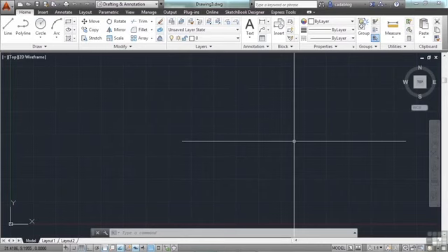Template files have a different format than regular AutoCAD files. You can tell them apart by their file extensions. You probably noticed that. A regular AutoCAD file has a DWG file extension, while a template file has a DWT. In all honesty, you could use a regular DWG file as your template if you wanted to. Just open it as you would any existing file and have at it. The danger with doing that, though, is that when you save the file, any changes made will be saved to your template. And so the next time you go to start a new file, you may have project-specific information in there, or maybe there's something missing that you deleted because for your drawing file, you didn't need it. So try not to do that.